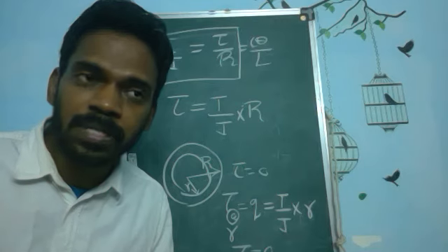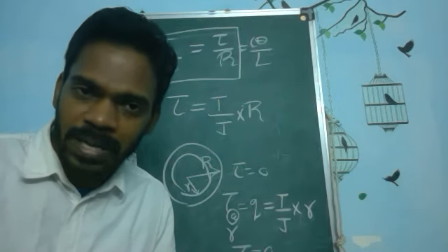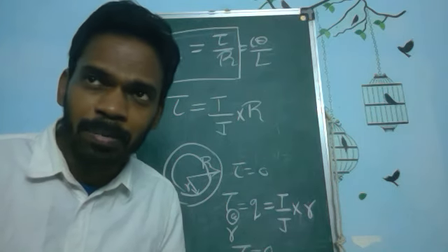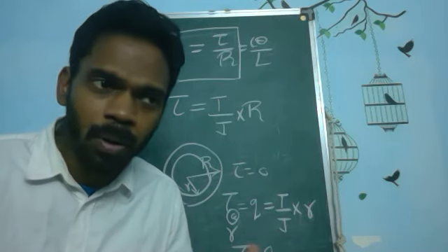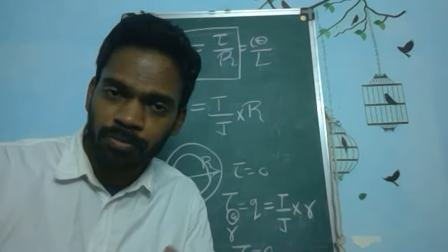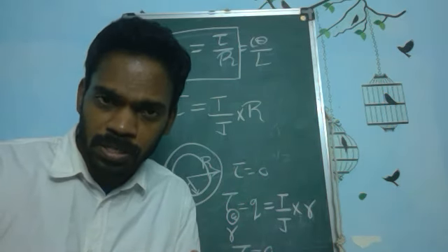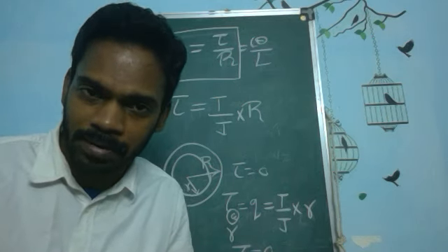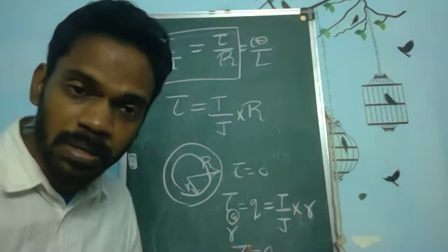This gives us an inspiration to design the propeller shaft as a hollow shaft, but you also have to do other analysis. Maybe you want to treat the shaft as a bar and do the analysis. You have to treat the shaft as a beam and try to find the bending moment. Shear stress is generated and you must make sure that the stresses are within the limit. You also have to do the modal analysis. But of course, this is a very good start.